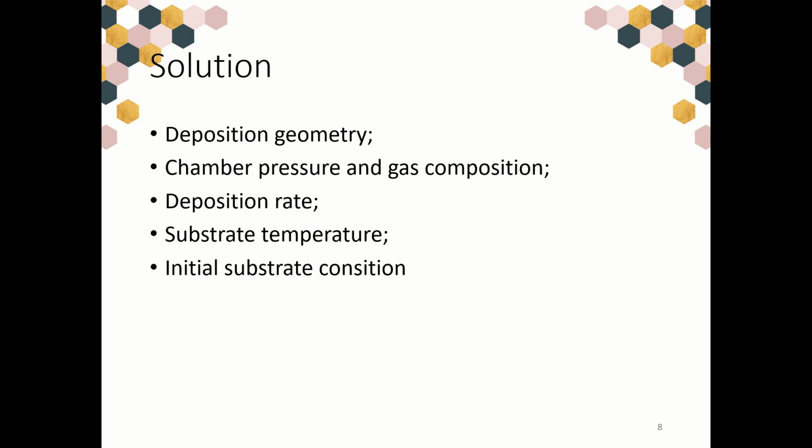The substrate temperature. It is crucial to identify that radiative heating and vapor condensation will heat the substrate, which is important for low melting materials. Therefore, before starting the research on glancing angle deposition, it is important to search about these materials.